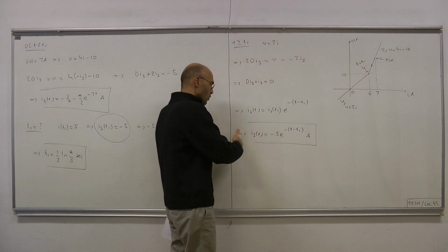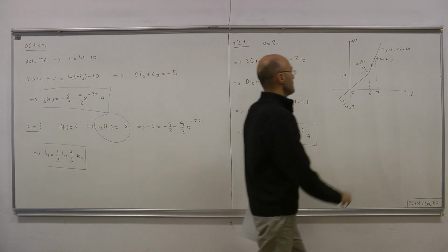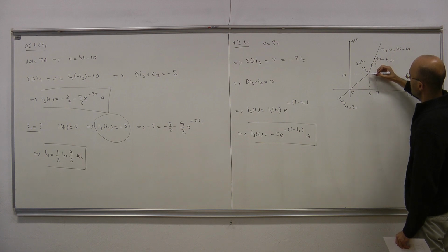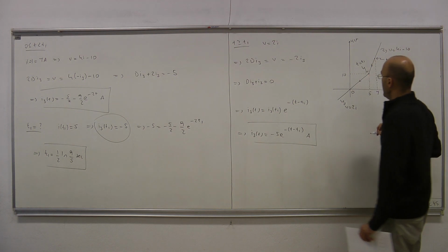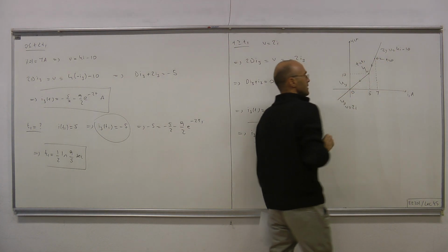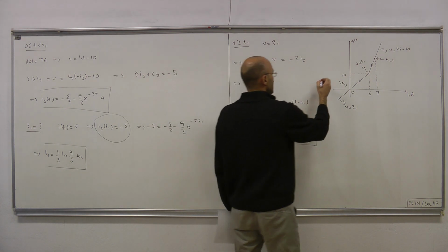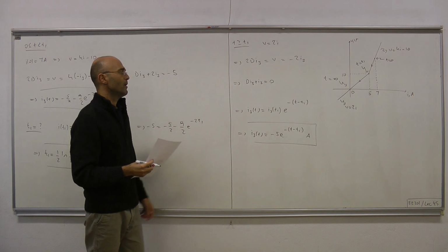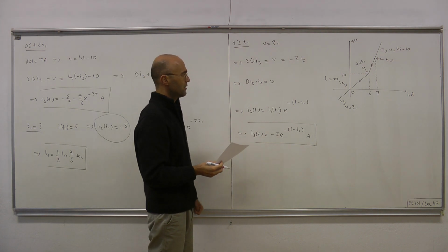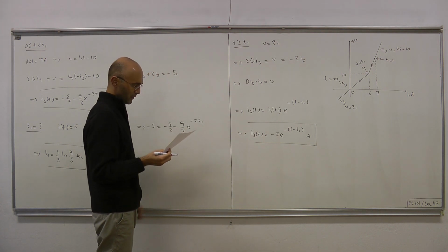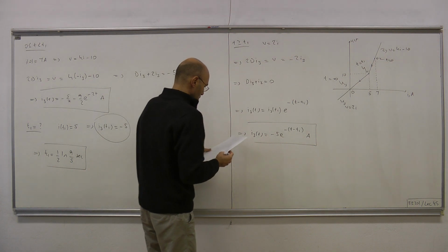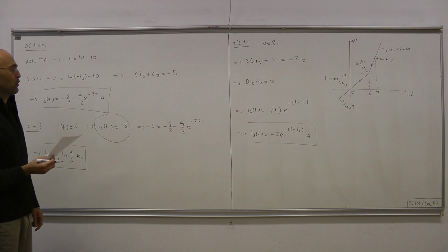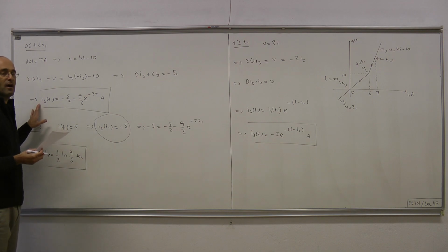So I3 going to 0 means that I, from 5, is going to 0, and it will reach 0 exactly only at t equals infinity. Therefore, we don't have to worry about another change in our differential equation. So our analysis is complete for I3. We have figured out I3 in piecewise fashion.